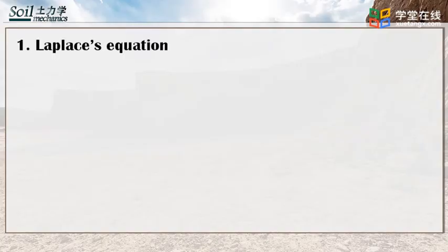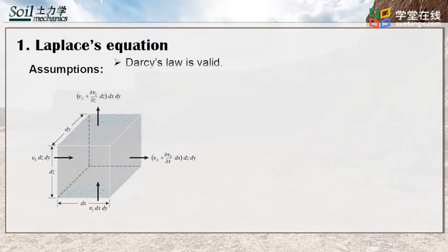In the last lecture, we've learned Darcy's law and one-dimensional flow through soil. Today, we focus on the two-dimensional problem. The Laplace equation and the flow net will be presented in this lecture. In two-dimensional flow, Darcy's law is still valid, and the fluid is assumed to be incompressible.